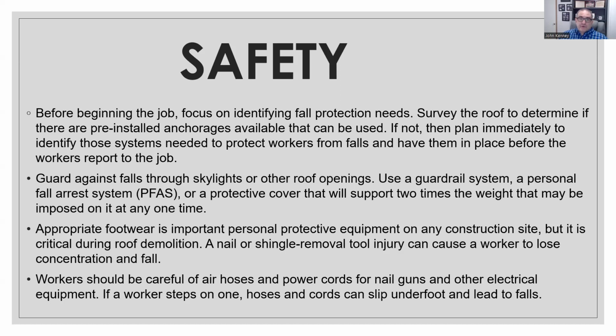So if you're going to use full tie off or safety rails, whatever that may be, have your plan in place first and make sure safety setup becomes job number one. Guard against falls through skylights and other roof openings. Use guardrail systems, personal fall arrest systems, or protective covers that will support 2 times the weight that may be imposed on them at all times.